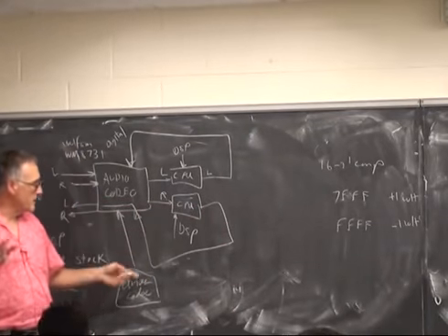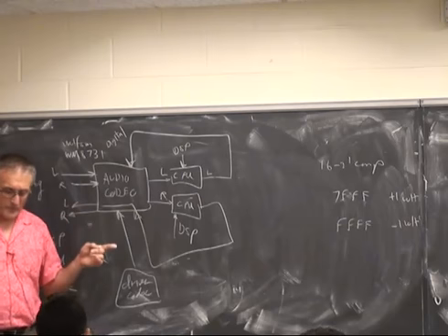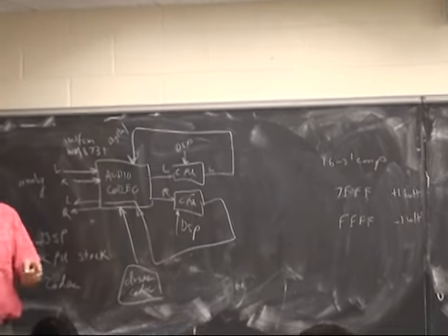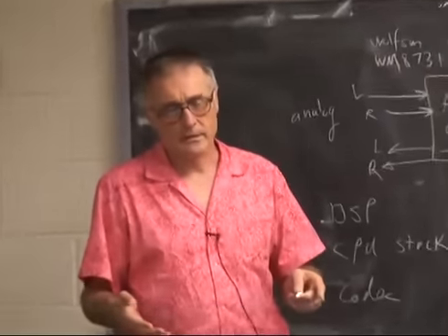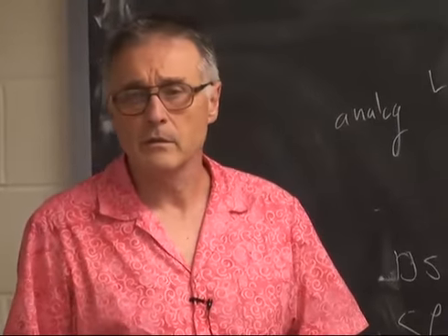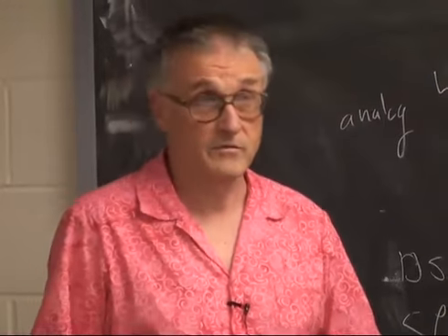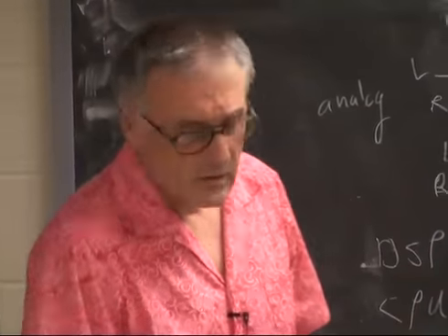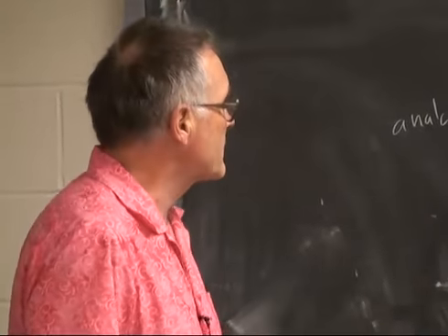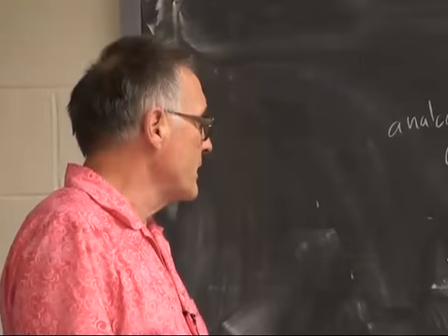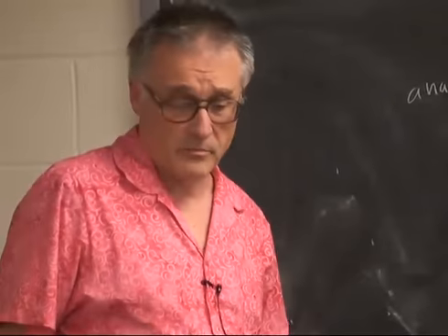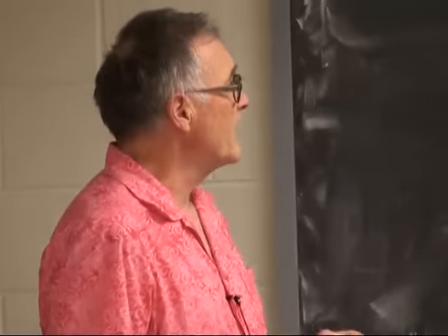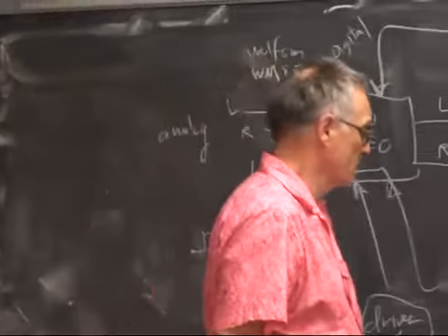Now, inside this driver, or inside the interface that you don't have to write, your data is going to be serialized and blasted out of a serial port at a fairly high rate. 16 times 48 kilohertz, in fact. So we need to talk a little bit about that whole process. But I think let's start with the CPU. So you're going to want to start reading up on Lab 2 soon.